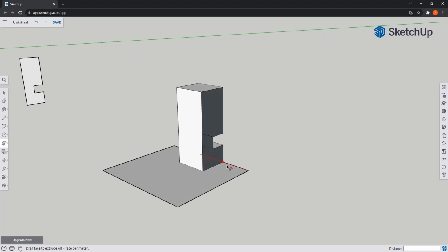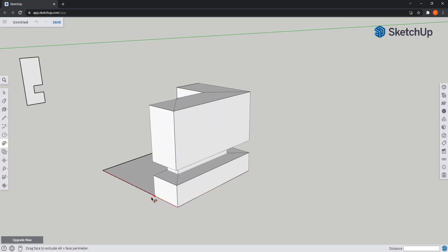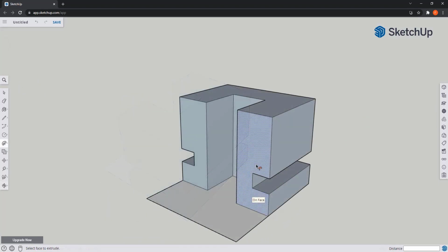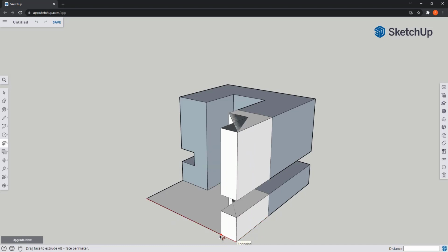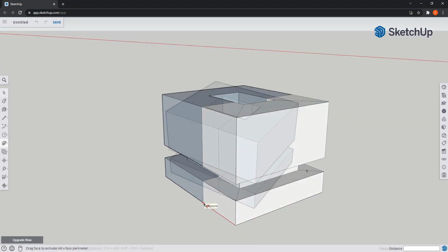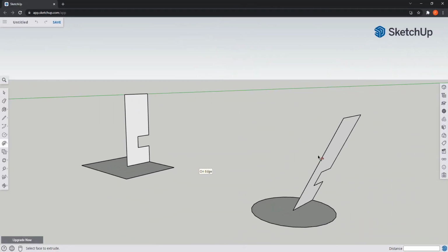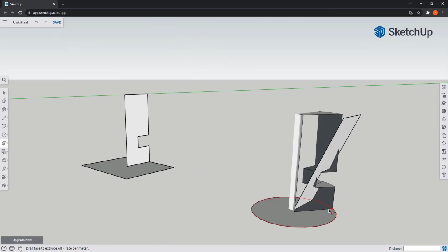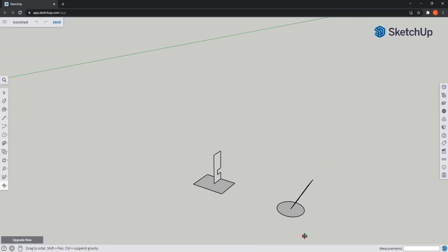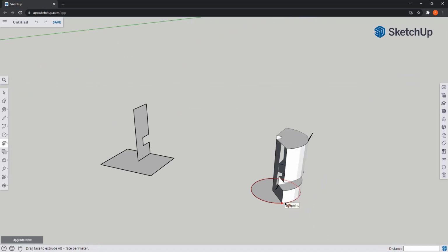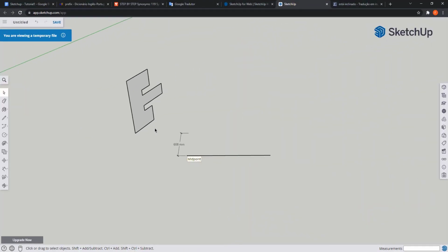In this case that I have a rectangle below, I can use Follow Me in the same way as I did for the circle. Then if I stop anywhere, I can continue later creating a second solid next to the former one. One important tip: it's not required for the face to be perpendicular with the path. If it's tilted a bit, like here, I can still model it along the line. And even the path line doesn't need to intersect the face. In this situation, I model the figure using the perpendicular distance from the line.